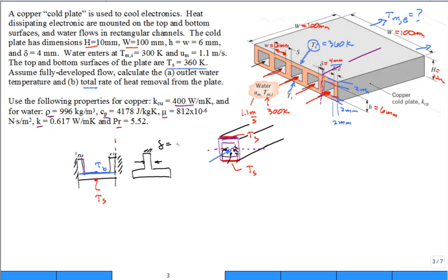The thickness, T, that's our traditional symbol for thickness. T is equal to delta equal to 4 millimeters. Then we have convection or heat transfer coming up and going out that way, as well as that way, conduction and convection off of that fin. I know I'm jumping around here for different sections, but some of the fluid would be flowing in that section, some in that section. If you look at it, it's the same as here in the bottom half.